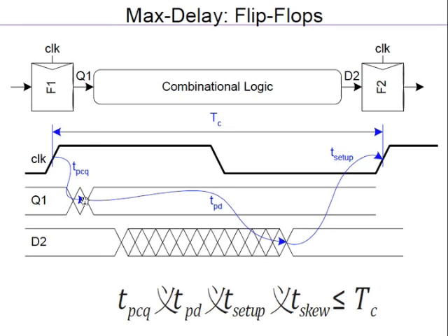This is called T propagation from clock to Q, TPCQ, the delay of propagating the data from the clock rising edge to the output, where it is stable and ready, and the next stage can start working on this data. The data flows through, and there is a propagation delay for it to appear at D2. After this delay of TPD, D2 stabilizes to the correct value.